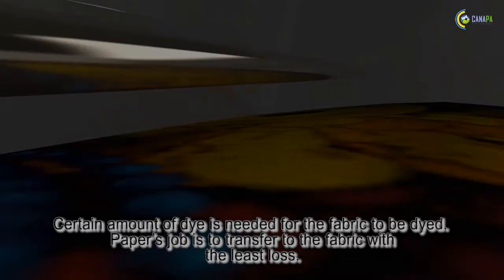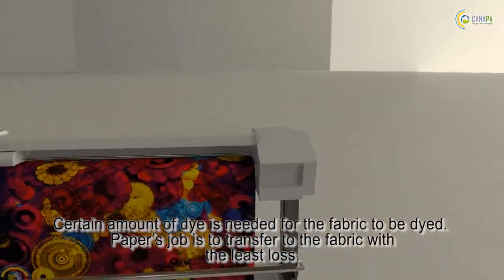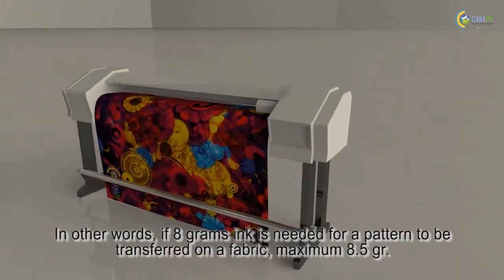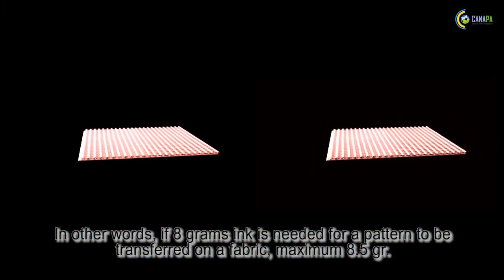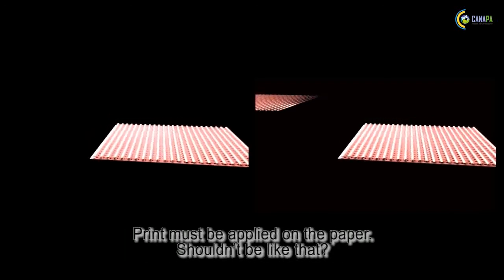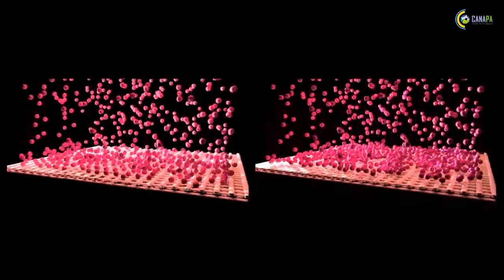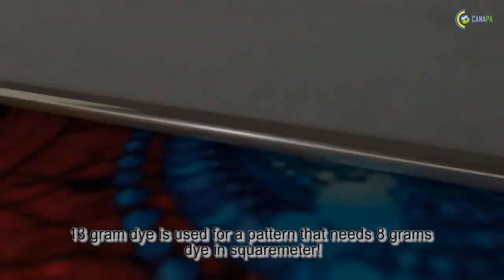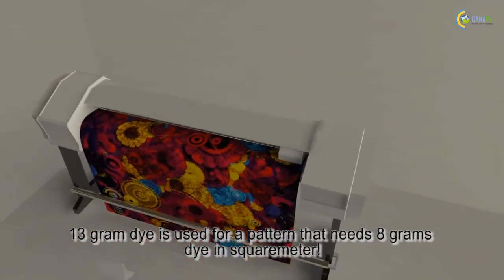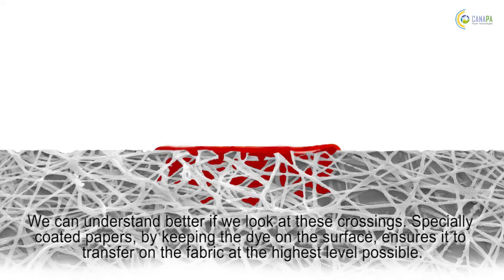Certain amount of dye is needed for the fabric to be dyed. The paper's job is to transfer to the fabric with the least loss. In other words, if 8 grams of ink are needed for a pattern to be transferred onto a fabric, a maximum of 8.5 grams of print must be applied on the paper. Shouldn't it be like that? Well, is this the case with regular papers? Let's see. 13 grams of dye is used for a pattern that needs 8 grams of dye in a square meter. Why is this? We can understand better if we look at these crossings.